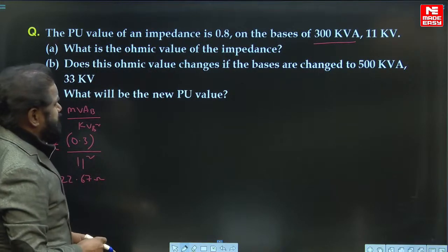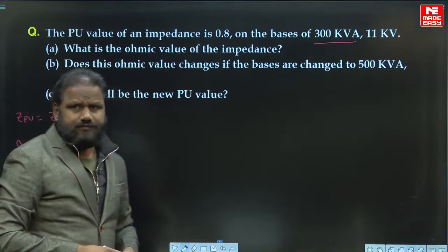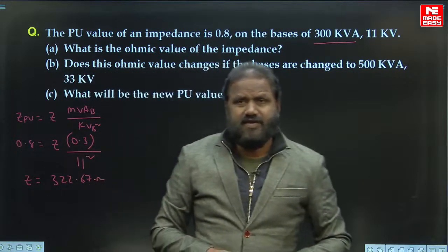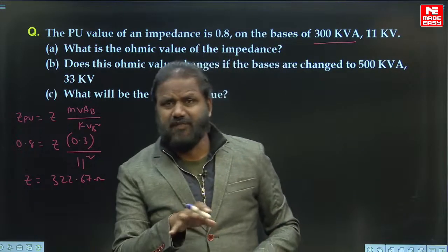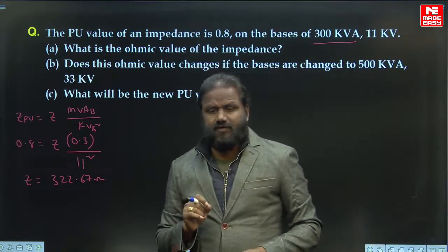Does this ohmic value change if the bases are changed to 500 kVA 33 kV? No. If the base value changes, the ohmic value does not change. If the base value changes, the per unit value changes. What is an impedance?